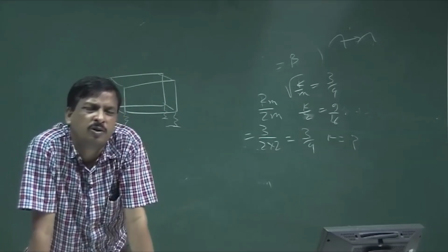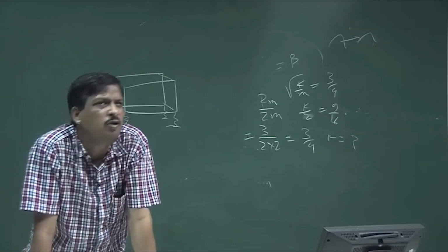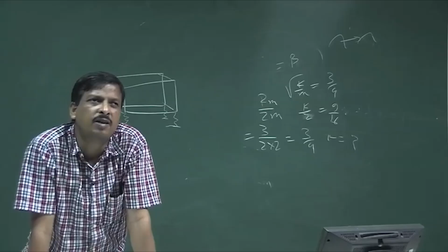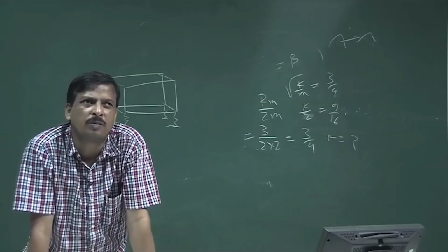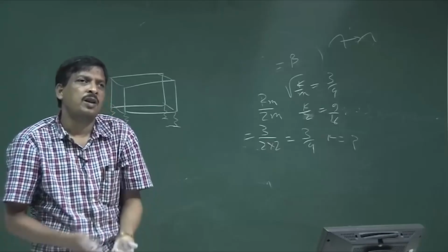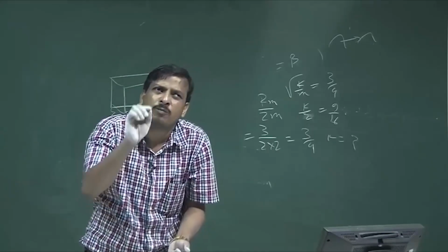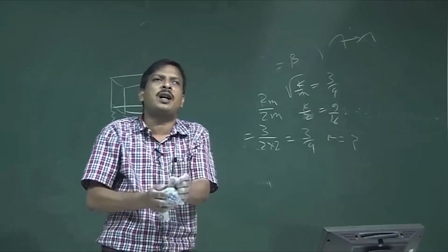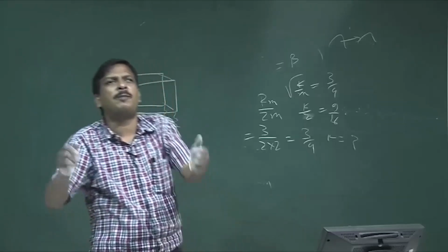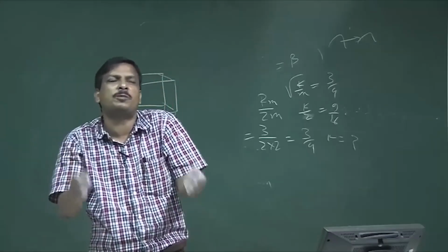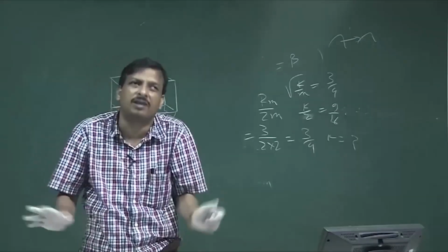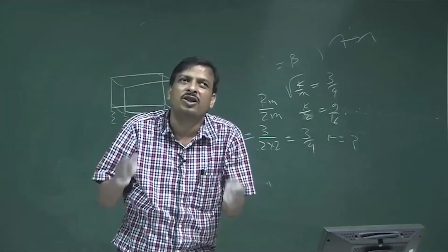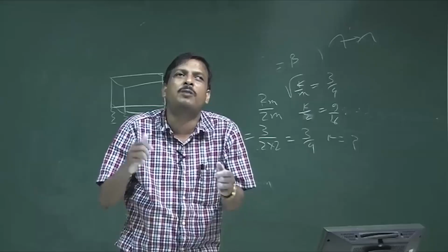Can I find out the resonance frequency of that system? Can we draw the equivalent mechanical circuits of that system? Can I find out all the other characteristics of mechanical motion? So, you see that the problem will not be given as a bookish problem. A practical problem will be given, let us say people will say I have a chiller plant, I want to install it with a rubber pad, and the rubber pad's spring constant and mechanical resistance are given. Then is this installation correct or not, or will it vibrate?